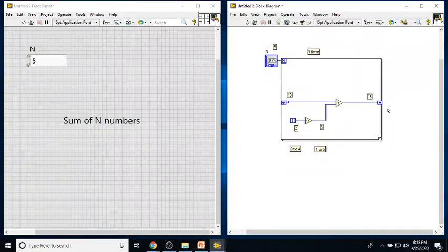So ultimately, what I'm holding on the shift register is nothing but the output of each and every iteration. I'm storing the output of each iteration in the shift register. Why? Because I take it again and add new data. With a 0, I add the first data; the output of that adding with the second data; the output of that adding with the third data; the output of that adding with the fourth data, and it keeps going in that way, right?